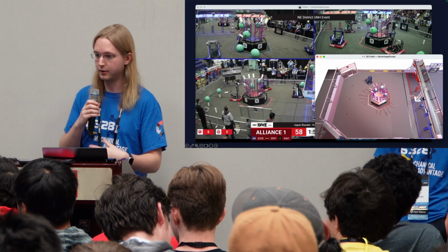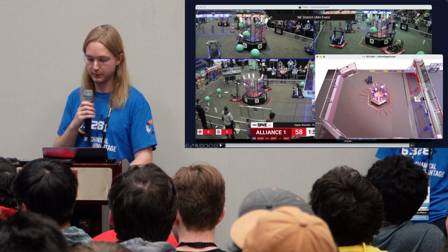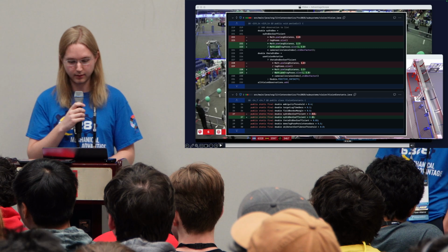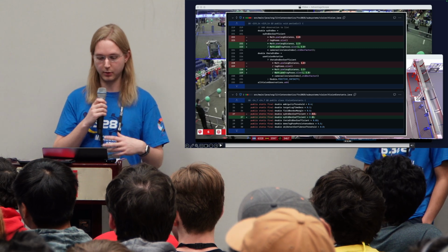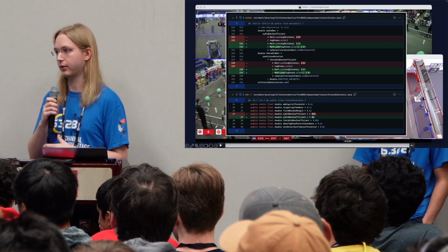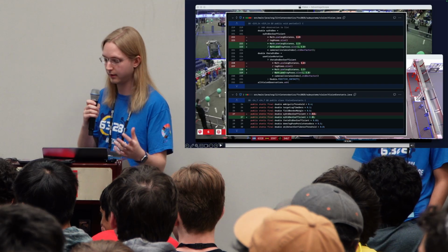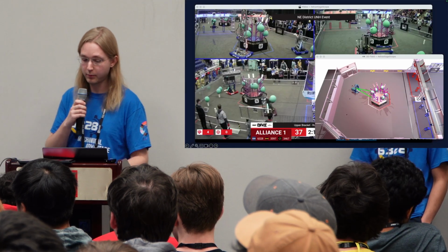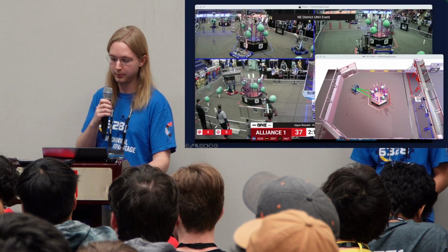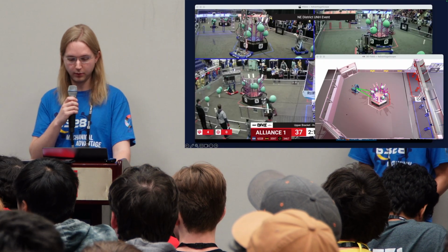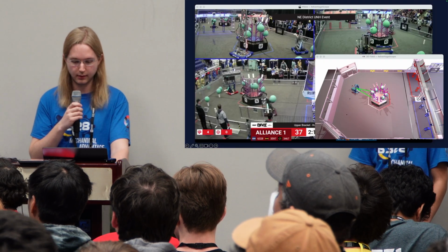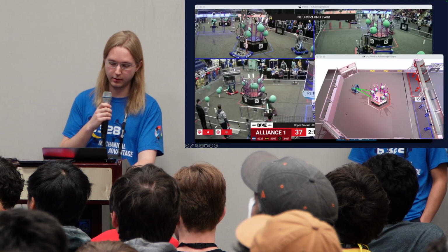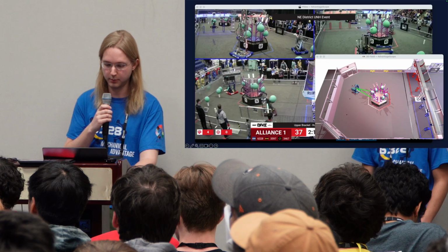Specifically, we wanted to change the way that standard deviations for vision measurements are calculated. We increased the trust in measurements from a large distance, we increased the trust with a large number of tags, and we increased the trust across the board additionally to reflect the overall accuracy improvements in the system. And without needing to test on a real field, we can now see what the estimated pose would have looked like with that new tuning. And in this case, we've hidden the individual vision estimates, but the blue robot, the translucent one, shows the new estimated pose from log replay.